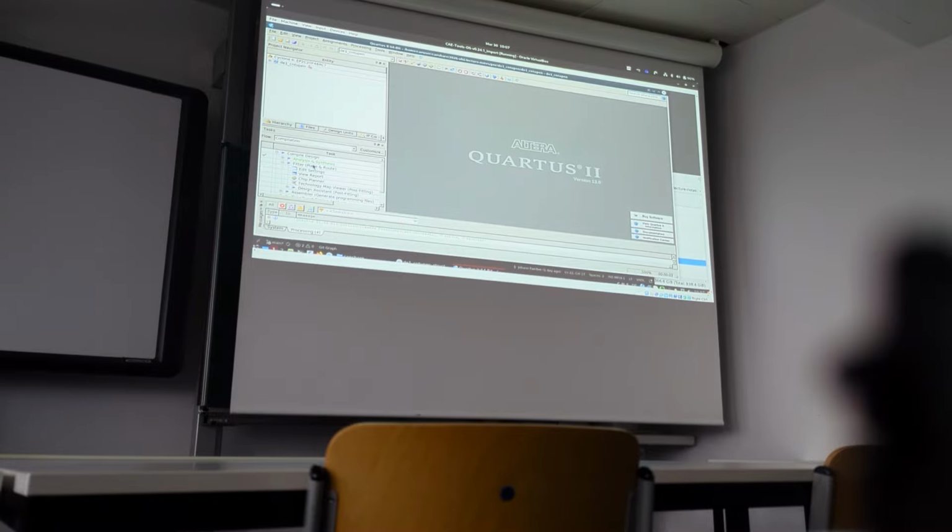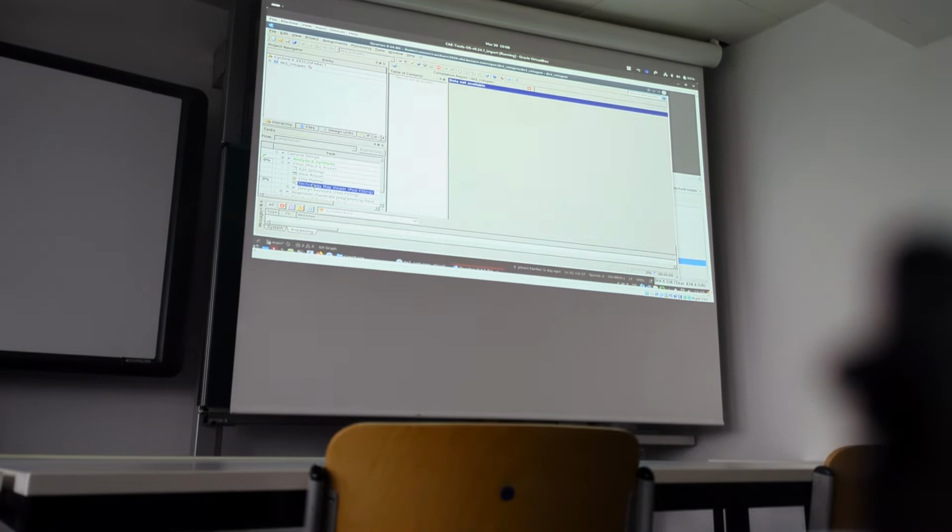Actually, in an FPGA they are already placed, so there's a kind of routing necessary here. Then after that, Quartus, our backend tool, knows exactly how many lookup tables are used to implement our design, and it will provide us with this information. We could also use this technology map viewer. We always get a report here.